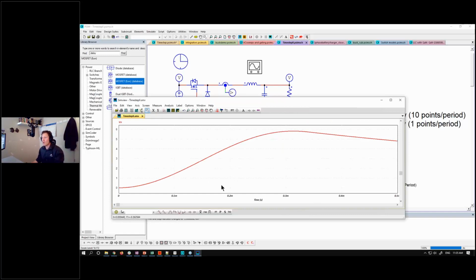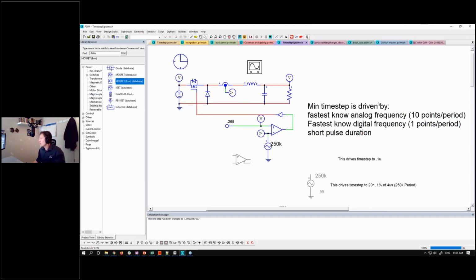If you want to change what's going on down here, if you go to axis, you can change the x-axis variable quite easily. And then, did you add a probe? I think I answered that. Another thing you can do is, when we're simulating, I'll show you how you can do runtime variables and polar plots while the simulation's running. There are some other things to talk about there. Okay, coming back.